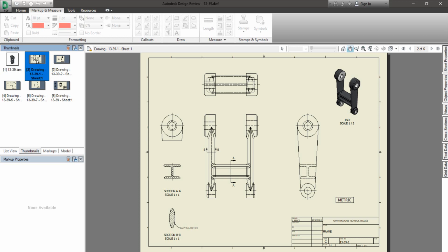Here's part number 1. This is a left side view, but it has been cropped. When you dimension an ellipse, because this is lofted, you only dimension the width of it, because no matter where you are height-wise on this thing, the length of the ellipse will change. So just dimension the width of it.